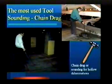This one's made with a bar and a couple of chains, but we happen to find that this one works very nicely. Now, you'll notice that he's got a very nice big one, but all of you engineers are dressed in suits, so every once in a while, you pull up your little one. And you can carry this along with you all day long and never get tired. Now, what does it sound like? It's a little hard to do it in here because I don't have good solid concrete and I don't have hollow. But you hear the hollow sound. That's what you're listening for. As you drag the chain across the floor, you're listening for that hollow sound.